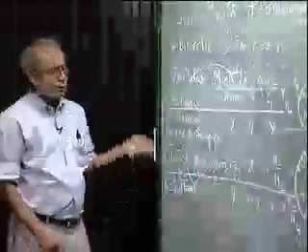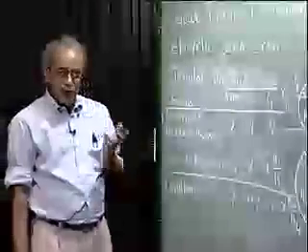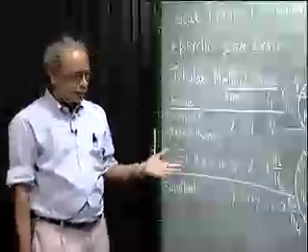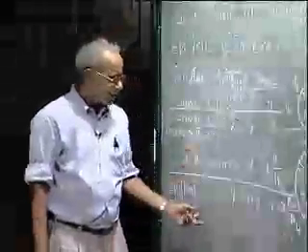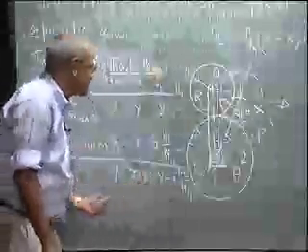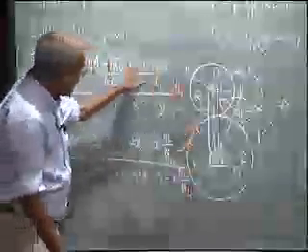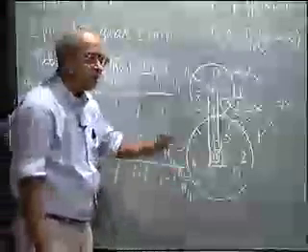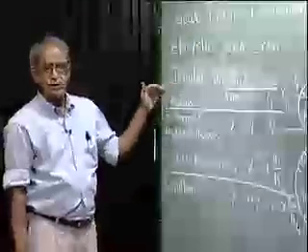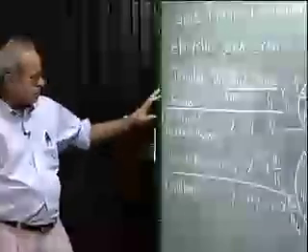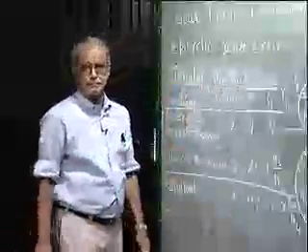Now as I said, it is a 2-degree freedom mechanism. So all the output speeds can be determined only if you give me 2 definite inputs. That means 2 of these speeds must be known, then only I can determine the third. So I get 2 equations by equating the given speeds, and I can determine x and y, and once I know x and y, I know the speeds of all the elements because they are all expressed in terms of x and y. Of course the number of teeth are given. This is the method that we shall follow, and I shall solve a few examples to show how to use this tabular method for analyzing epicyclic gear chain.